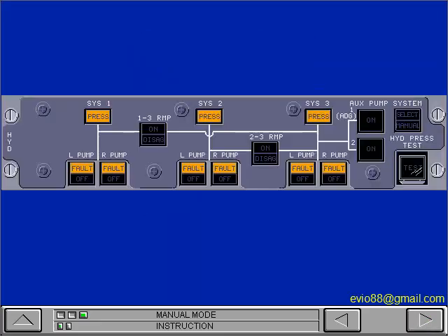Before you pressurize the hydraulic system, you must first make sure that the HSC is in the manual mode. The manual light shows that the system is in the manual mode. The 6 fault lights stay on during all of the procedures. The RMPs also come on when you set the HSC to the manual mode. You must turn off the RMPs before you continue.